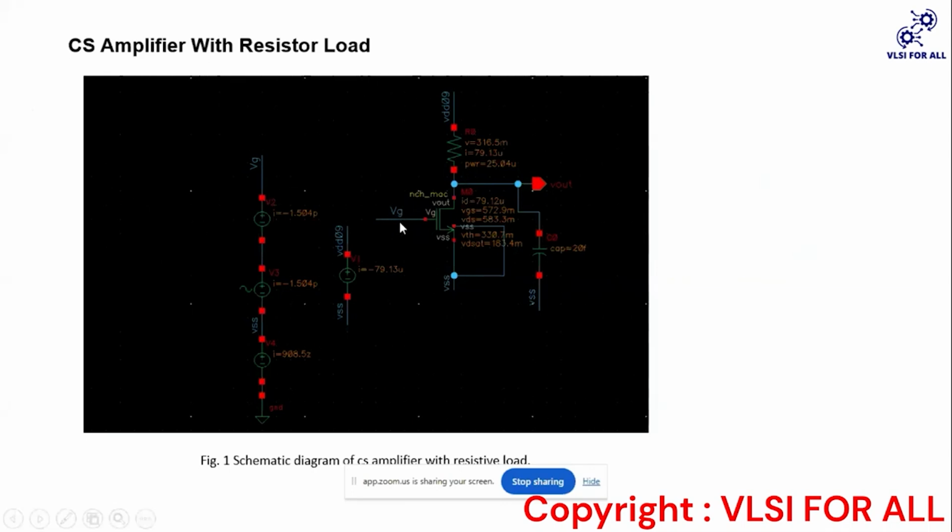So by changing this VG, the input voltage, our drain current is also changing, and hence our gm is changing. So we try to make the analog circuit less dependent upon gm. Gain should be less dependent on gm, because when gm changes upon changing the input voltage, then our gain will change,